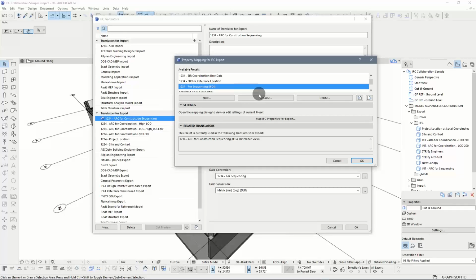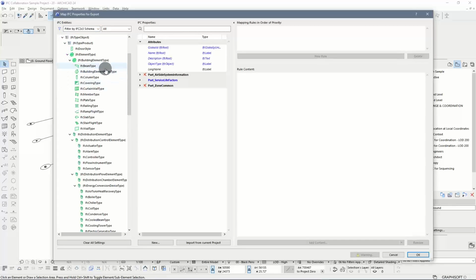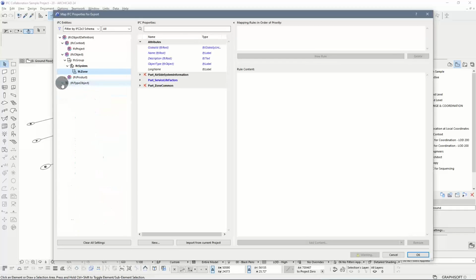It relates to creating relationships between that physical, or well, virtual element, and then an actor, and then a task, and then an event. And that's something that Archicad, since it is an architectural authoring tool, is not designed for. So you will see that even if you look for them, there's not going to be a particular P set or individual entities, either in IFC 4 or IFC 3, that will comply to anything other than building elements and the types. So you won't get to do that.